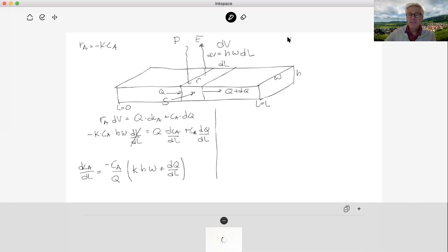And in this case, the P and E have unit cubic meter per square meter and hour, and S has the unit cubic meter per meter and hour. Because you know that rain falls, a number of cubic meters falls on the surface, but in this case with the seepage, there's a certain number of cubic meters that enters on the side for every meter in the wetland.